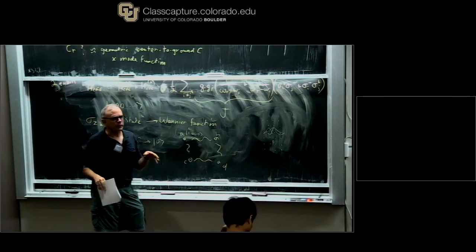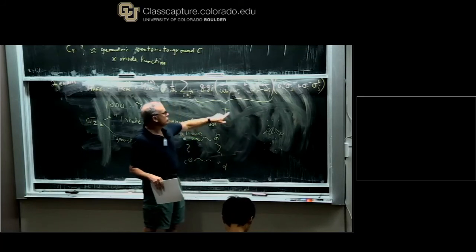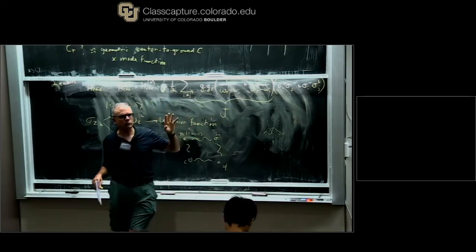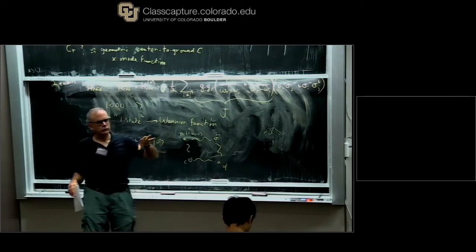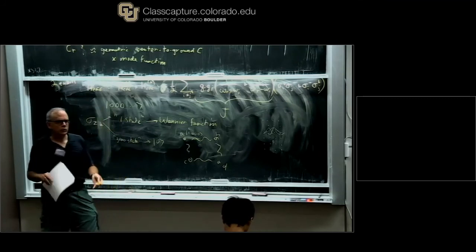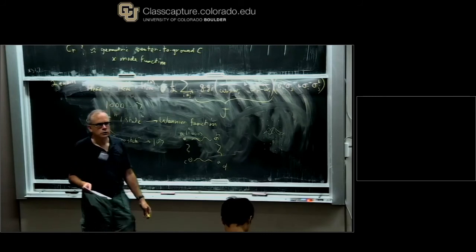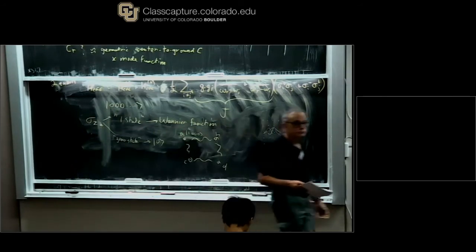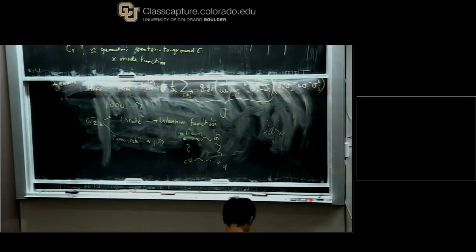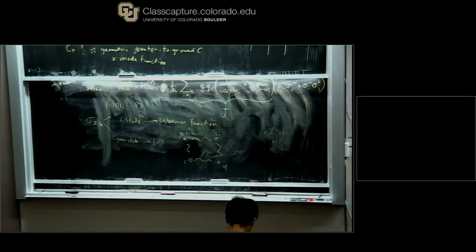So the direct coupling, the capacitor-only coupling, also gives something of this form, but you have less control over this. This you can actually have of either sign, and that's actually of some use. In the direct capacitance way of doing it, you only get one sign. It's only, quote, positive. And that can be somewhat limiting. I mean, not for the gate model approach to quantum computing. Yeah, sure. No, that aspect is independent of any details of this coefficient. It's just dependent on the fact that the effective coupling is of this form.